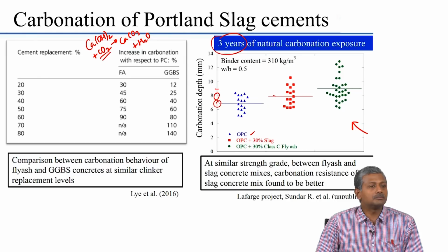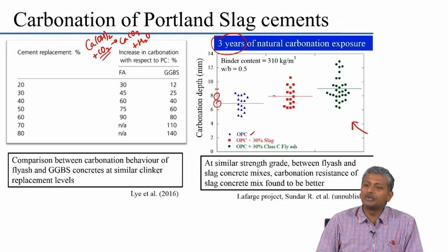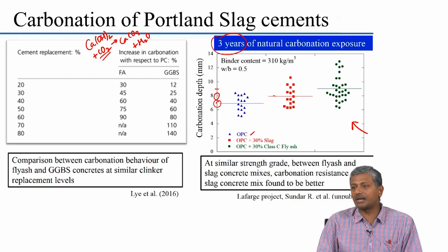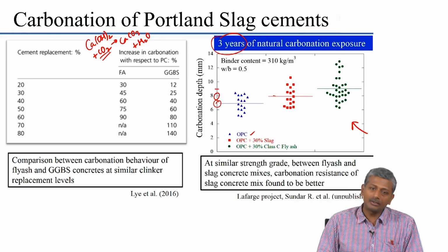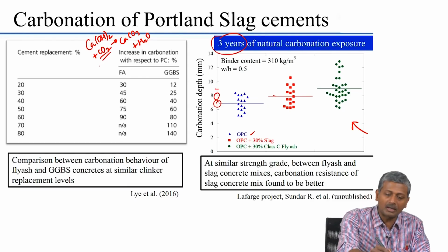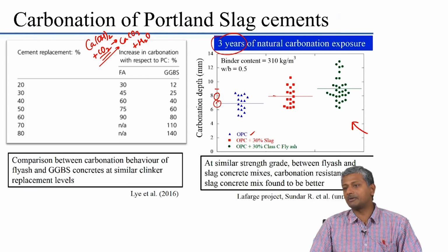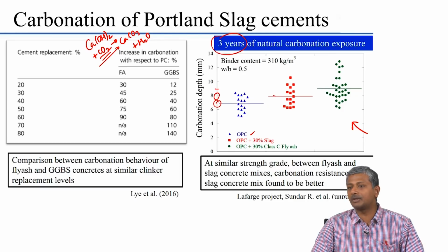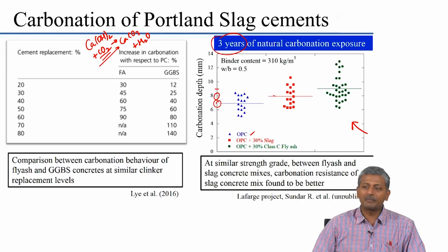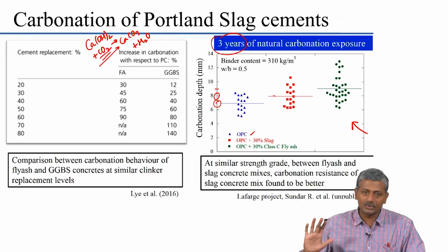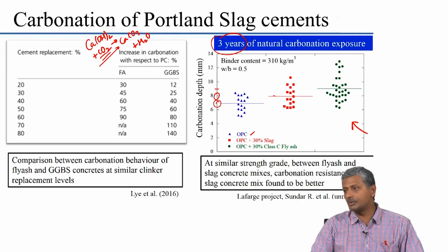Okay. Now, this lime is already reduced in a pozzolanic system or in a cement substituted system. You have less lime available, right. So, if the carbon dioxide cannot react with lime, what will it do? It will tend to react with other calcium bearing compounds like CSH. Okay. And because lime reaction with carbon dioxide leads to the formation of calcium carbonate that almost forms an impermeable layer on the surface of the cement mortar or cement concrete, that becomes a limiting process. It further slows down the rate at which your CO2 actually goes in.